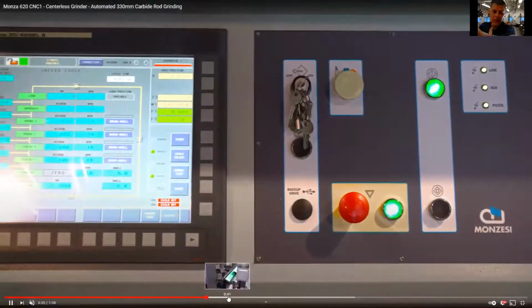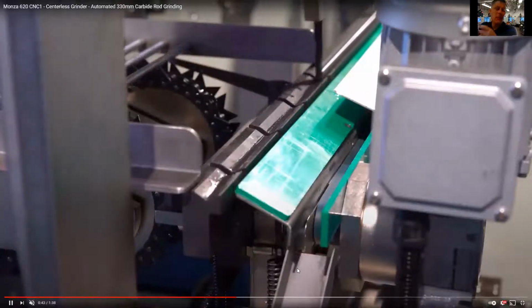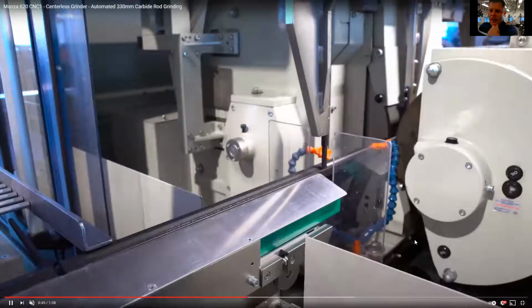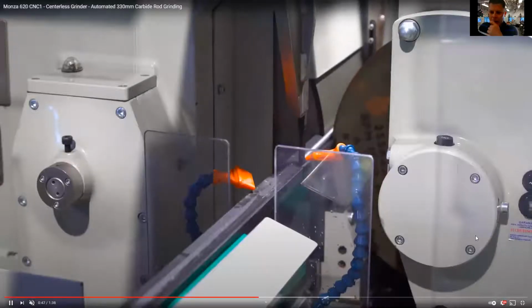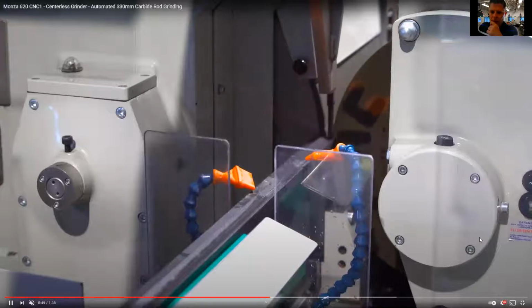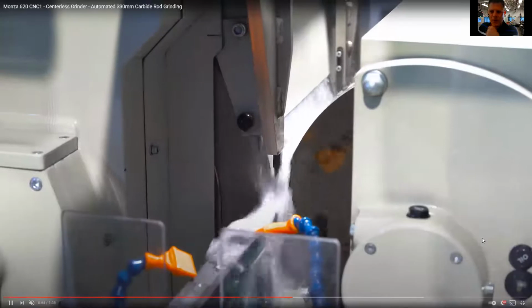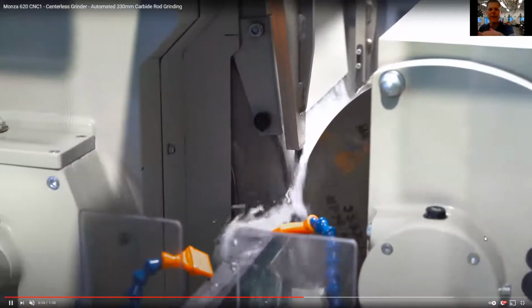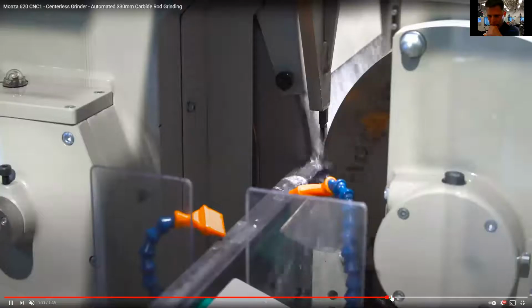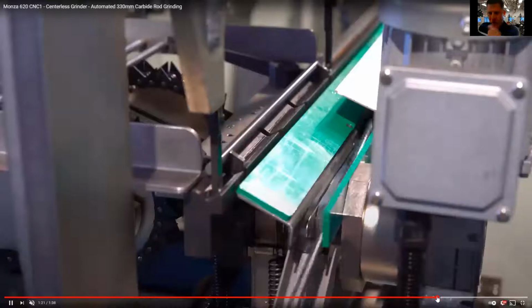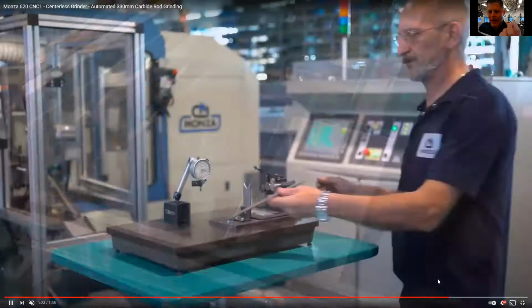So maybe I don't know what they needed these for exactly. This one's an automated cell, but you're gonna see it puts it into the centerless grinder right here, right? So the robot's moving it in. It basically lets it go back and forth between that centerless grinder. That's how we grind the entire outside diameter. Now, when it's all done, we'll come over here. We don't want to watch it grind for 2 minutes. It gets taken out and loaded on the chute.